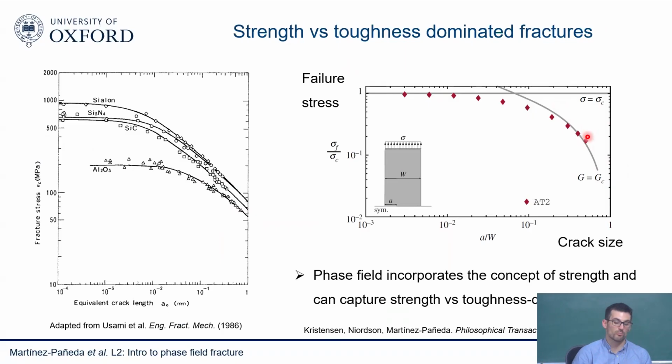I've seen people say, I know that I have a big crack, I'm very confident that I'm in the fracture mechanics regime, I'm dealing with an inelastic, elastoplastic material. So maybe I don't need to use the real strength, because that would require a very small element size, and I want to use a bigger element size. You can use a slightly different one and you'll be okay. But in principle, the protocol should be that my length scale is fixed. I can play with the elements, and they need to be small enough. They cannot be that large.